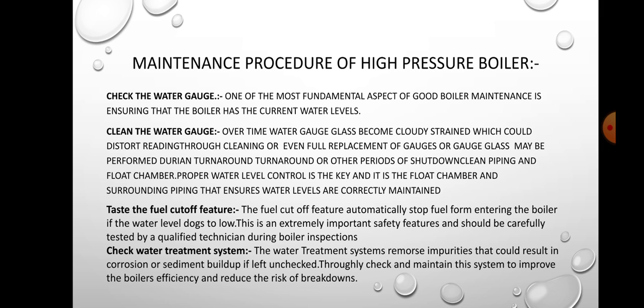Then clean the water gauge. Over time the water gauge glass becomes cloudy or stained, which could be distracting, so cleaning or even complete replacement of the gauge glasses may be performed during a shutdown.